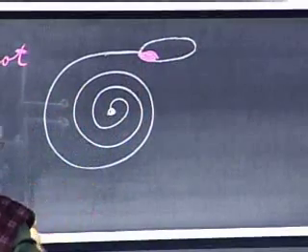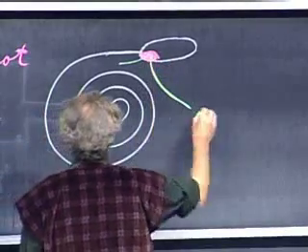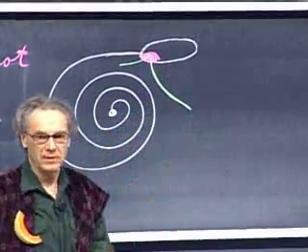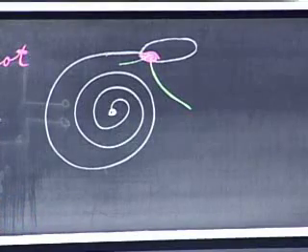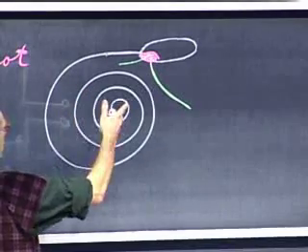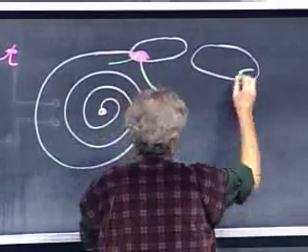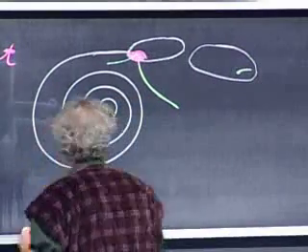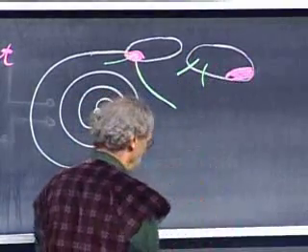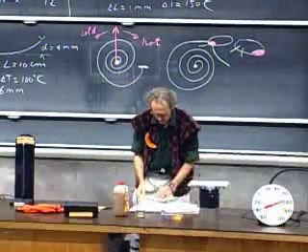The mercury rolls to the left. And there are here 2 wires, electric wires, one here and one here, which go to the heating system. And so when the mercury is here, which has a good conductivity, the heater is on. Now the room gets warmer and warmer and warmer, and the bimetal will tighten up, will curl even more. And so there comes a time that this glass thing will go like this, and the mercury rolls out. And when the mercury rolls out, here's the mercury, these contacts here are open, and the heater will stop. And that's in almost every room. Very genius device.